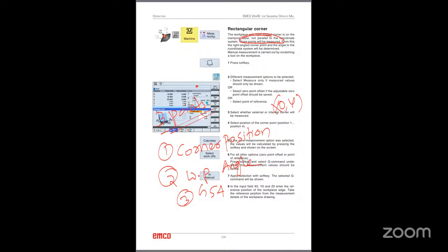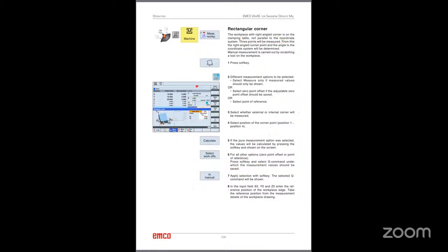So when will you use this function? If the workpiece is not clamped properly and there is a small inclination. You can use this on a rectangular or square block. If your fixture causes a small angle, and also you need the coordinates of X0, Y0.